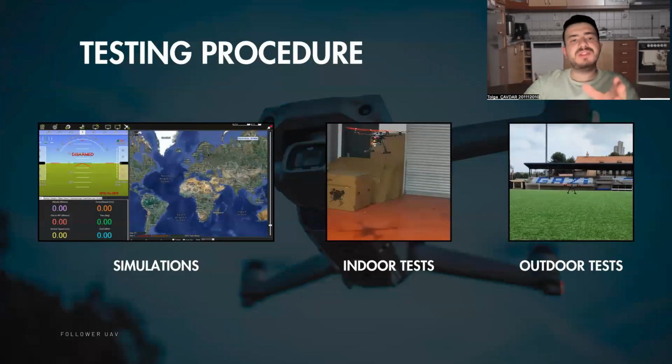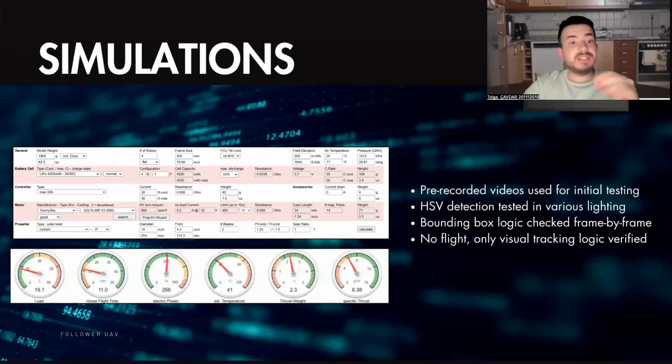We conducted a three-stage test process to evaluate the functionality of our system: simulation, indoor, and outdoor tests. Firstly, simulation tests were performed in a virtual PX4 environment with Mission Planner. Direction commands were generated by Raspberry Pi according to the red target detected with the HSV-based algorithm, and the effects of these commands were monitored via Mission Planner. This test was a critical step to verify the control logic before moving on to physical flight.